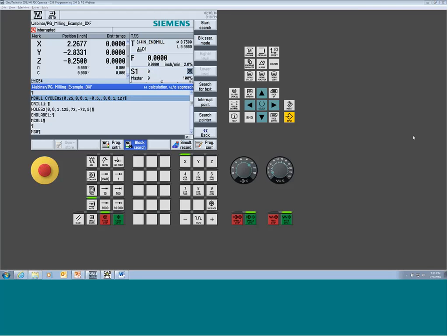Here's a different question. How to force the spindle to always stop at a specific angle at any time stopping at the end of an auto program or MDA. So there's not any way I'm directly aware of to force it as to where it's going to stop, but you can position your spindles. At the end of a program, if for some reason you wanted it clocked to a specific location, you can position a spindle with what's called an SPOS command.